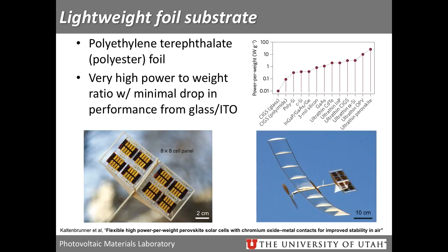The reason they wouldn't be used in space is just the stability. They're metal salts, so any water ingress inside the cell will destroy the cell essentially really quickly. And so they do not have the long-term stability yet necessary for space applications. Right now, I think the stability of them is on the scale of weeks, whereas standard silicon or other thin films have a standard warranty of about 25 years.